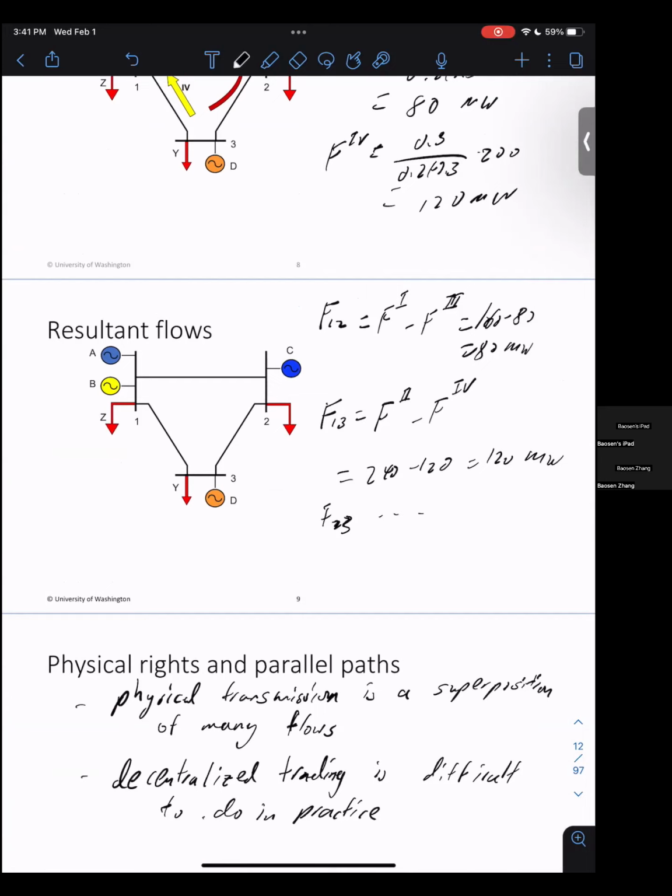So that's where the complication comes from, right? You would think, why not have a completely decentralized market where sellers and buyers can just come to their own agreement, and you can take the market system operator out of the market. The reason is that because of the physical power flow, someone needs to do the addition and subtraction at the end. And because of this feasibility constraint, it is very difficult to implement completely decentralized bilateral trading.